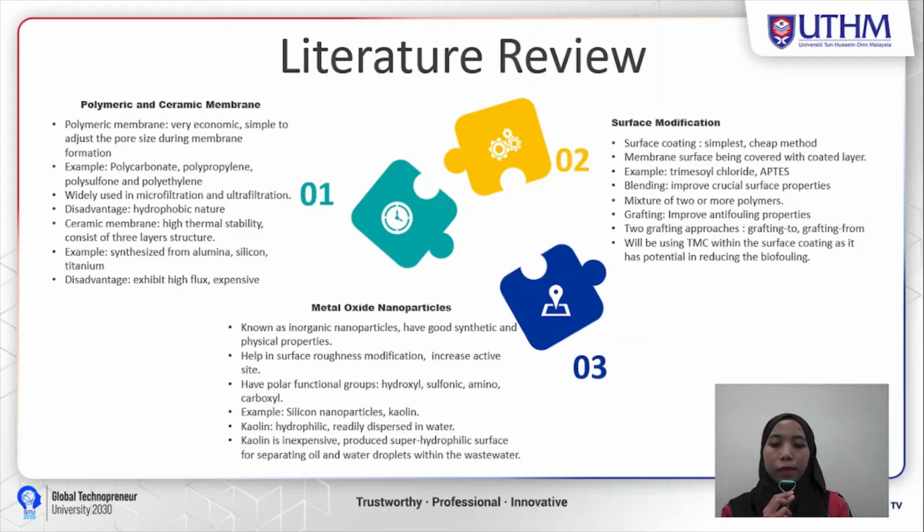Next is the blending method. This method involves the mixture of two or more polymers. Blending modification is usually done before the membrane formation, where a hydrophilic component is added into the membrane casting solution. The blending method will improve the crucial surface properties.